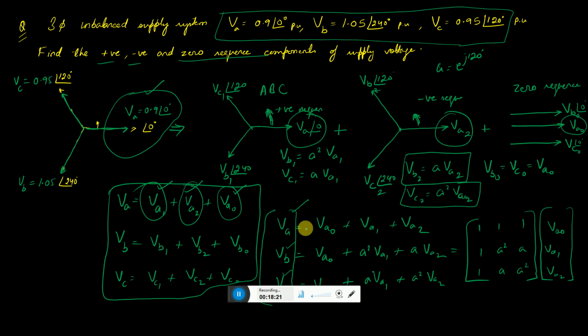All these things we discussed elaborate that unbalanced voltage leads to, apart from positive sequence, negative sequence and zero sequence voltages. The zero sequence voltage will lead to zero sequence current, and the negative sequence voltage will also lead to negative sequence current. That will all degrade the quality of the output.